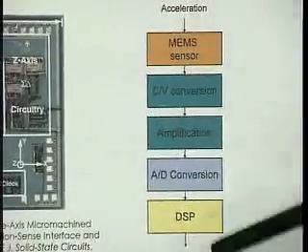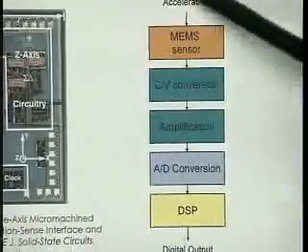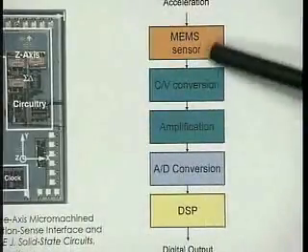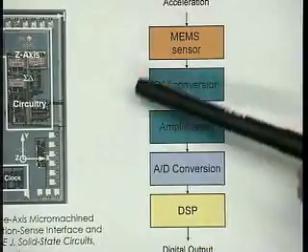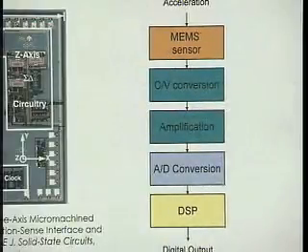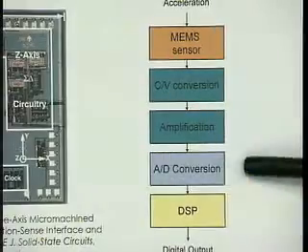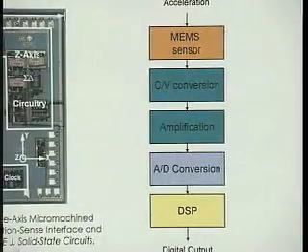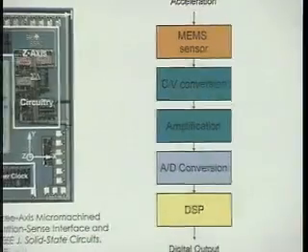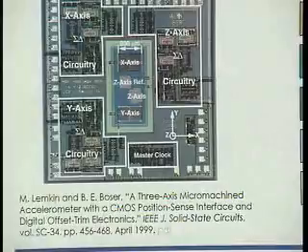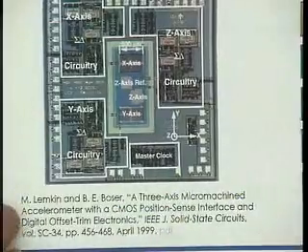So a typical analog circuit application looks something like this. There's some kind of a sensor here. This is MEMS stuff. Then there is a very sensitive analog circuit. Then there is an A to D converter. And now the rest is digital, right? And the digital part we haven't even bothered building here. There's pads, and then it goes into an FPGA, and the FPGA realizes the digital stuff.